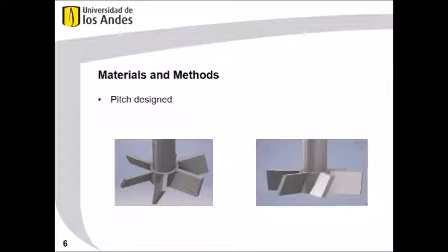Furthermore, a bibliographic search was made with the purpose of finding an appropriate impeller that fulfilled the objective of generating a greater shear stress than the Rushton impeller. With this in mind, the pitched blade turbine impeller was designed in Autodesk Inventor, because it was found that the average shear rate was higher for the standard 45 degree impeller.